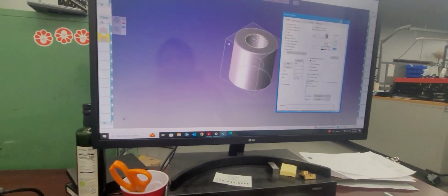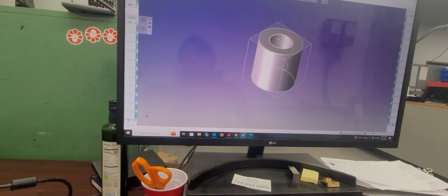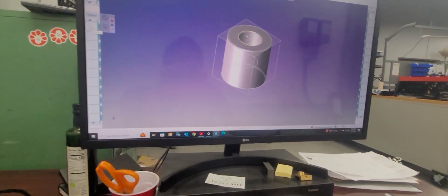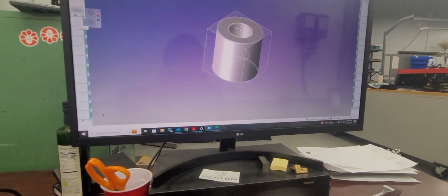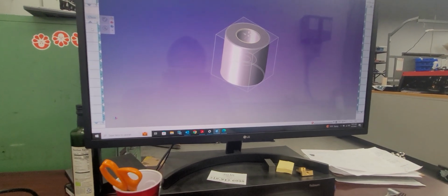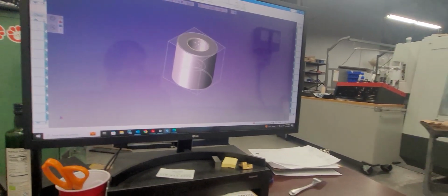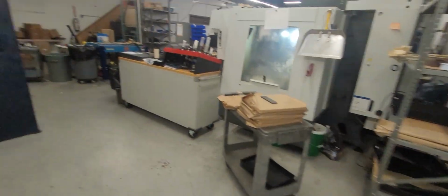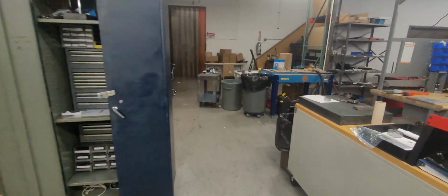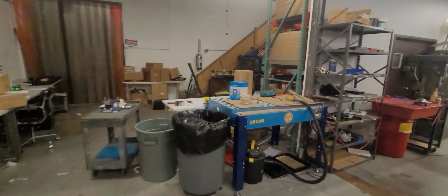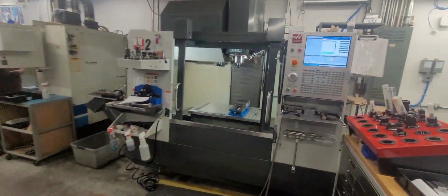Because I'm always programming off these process macros, I've got SFM for everything: tool steel, stainless, aluminum. And because it's always pre-organized, it leaves very little room for error. So that's how I load my tools up, that's how I stay efficient, that's how I can rough out and program a pocket in next to no time.